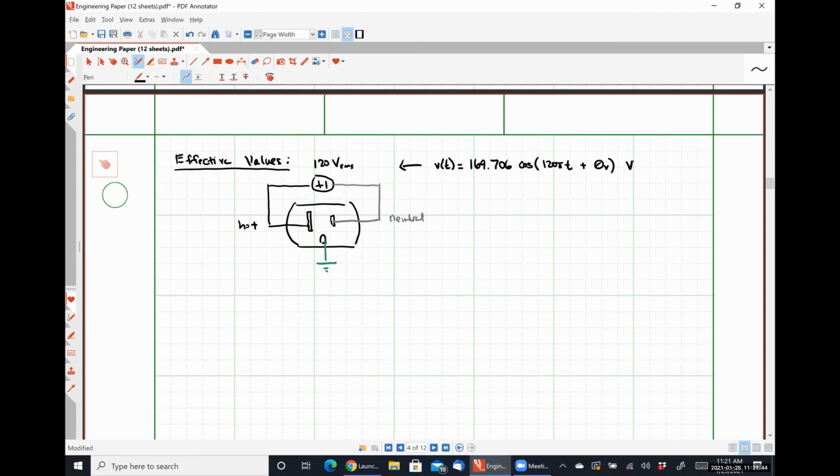But having to carry around all of that information would make most of the math and analysis in designing electrical systems far too tedious. So instead, electrical engineers developed the concept of an effective value. An effective value for a voltage waveform is a DC representation of that same signal that would deliver the exact same amount of average power to an arbitrary 1 ohm resistance, okay?